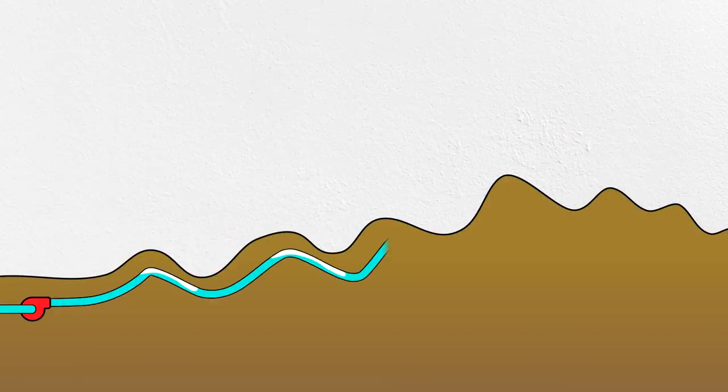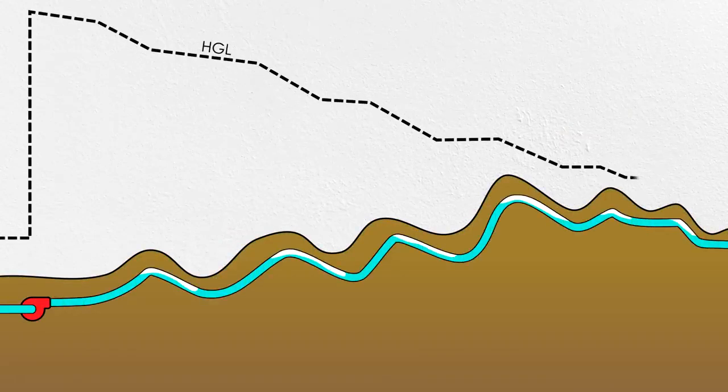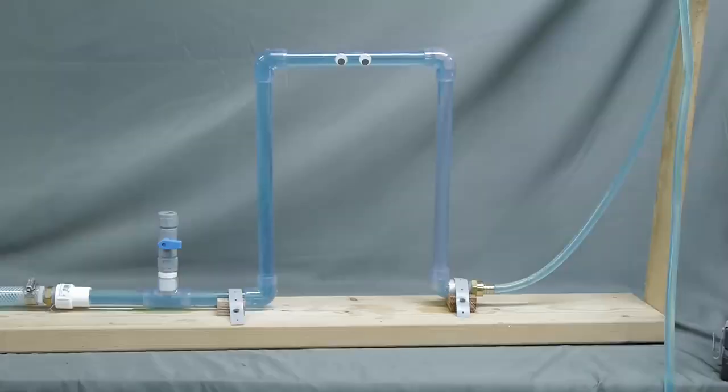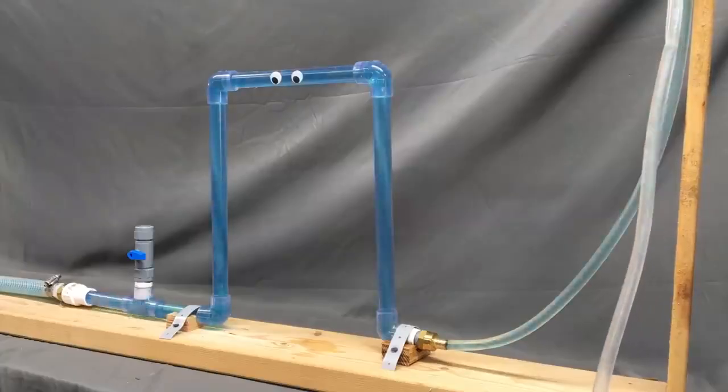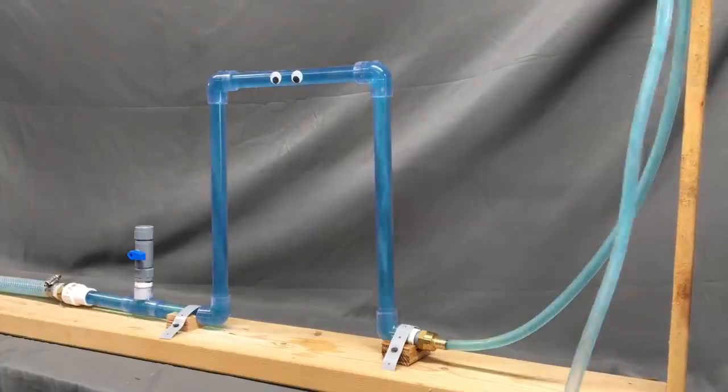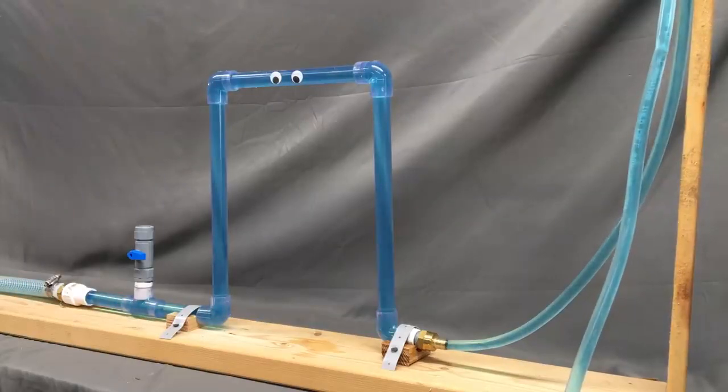Consider a long pipeline with lots of undulations. If you use a single pump to overcome all that airlock, the pressure rating of the pipe near the pump will have to be enormous. The second option is just to design pipelines that don't trap air. If the flow of the fluid in your pipeline is fast enough, trapped air will just be blown out. And if there aren't any high spots in your pipes, there won't be anywhere for it to be trapped in the first place. Again, that's not always feasible.